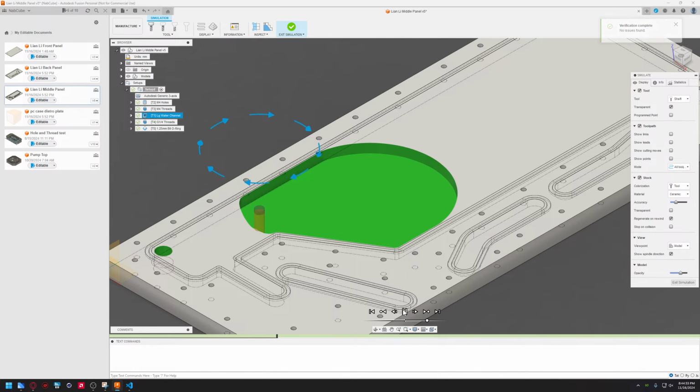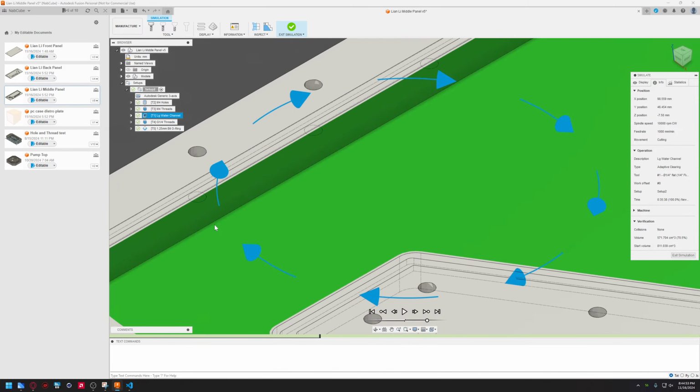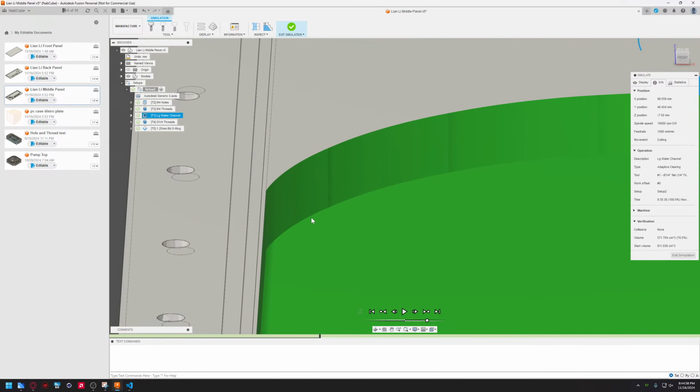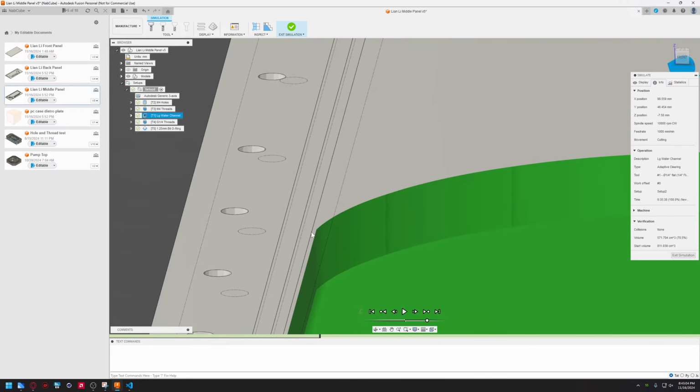But if I pause it here, instead of it being down the 850, or 8 millimeters, it's actually leaving 0.50 on this. And it should be leaving, I don't know if you can see it, but it should be leaving this 0.50 here. This actually should be 0.5 there to there. So I can come in with a finish pass at a slower ramp or a different type of cut.